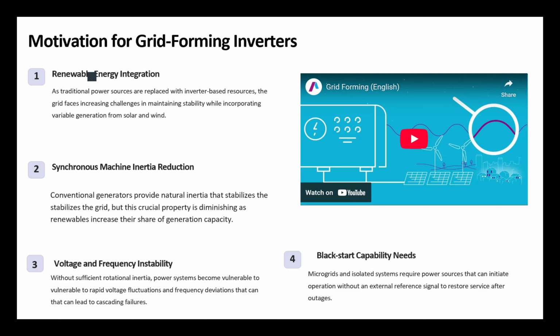That means the stability of the inverter-based resources, the output voltage of the inverter-based resources, is very fragile. It doesn't have inertia and it instantly answers to any change. Sometimes some changes you have to ignore, because they're temporary and wouldn't affect anything, but inverters do not do that.